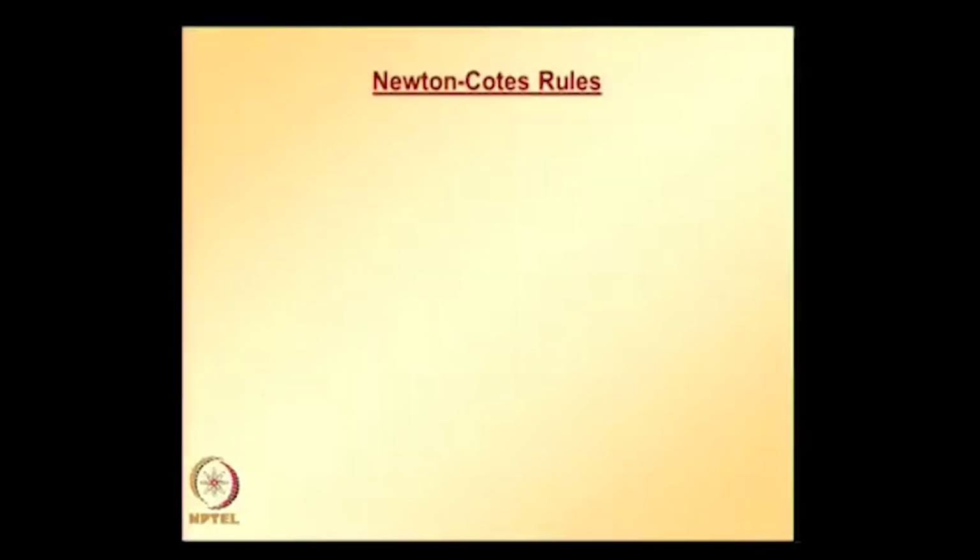In the next few lectures, let us look at various types of integration schemes, and this helps us to get an idea why Gaussian quadrature is preferred for finite element calculations. So, to start with, let us look at what are called Newton-Cotes rules, and under that we have the first one point rule or rectangle rule.